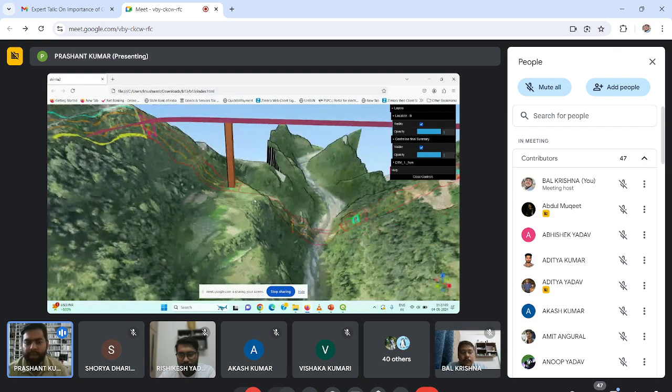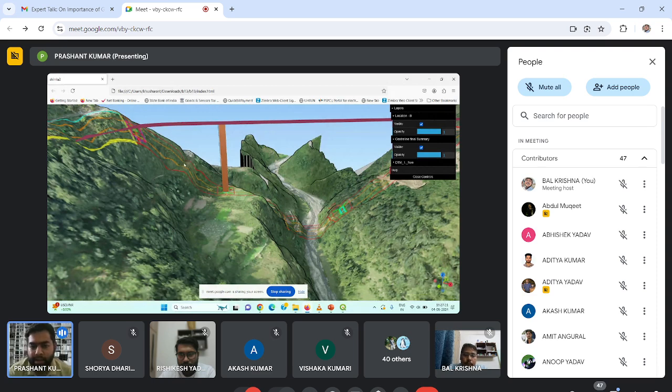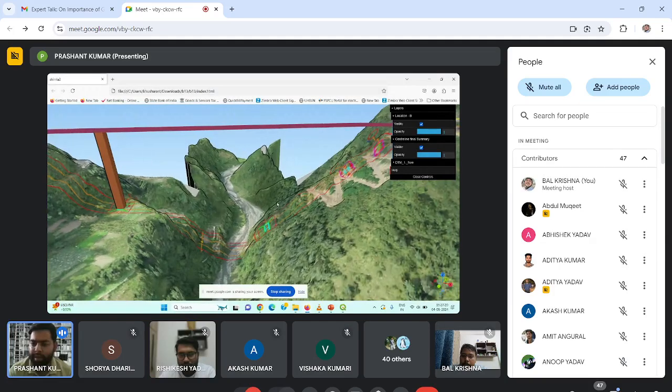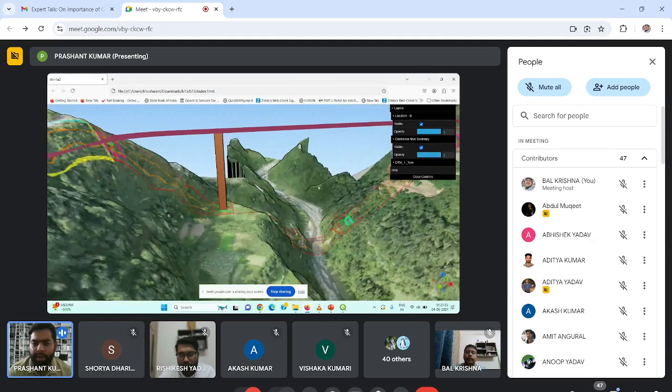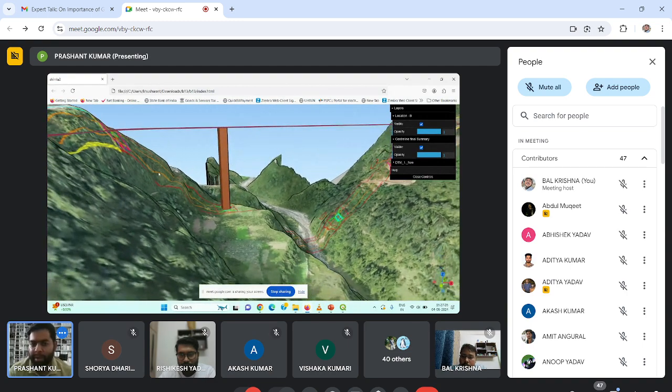Now another critical thing which I would like to mention, that guy has also placed a foundation here at point B. If you all would remember, A, B and C, then D was here, then E was here, then F was here. So you see, a foundation is not at all possible at B location, because cutting it would endanger this foundation, and slope stability is always going to be a concern when putting a foundation here.